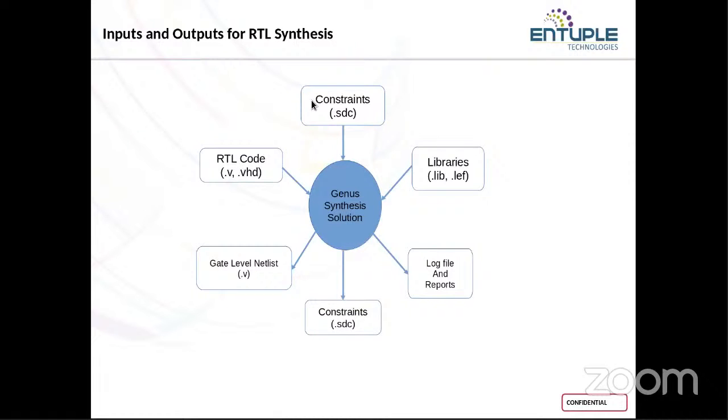So whatever SDC we are giving, that is user understandable, and whatever SDC the tool generates, that is your block level SDC file, which basically represents your individual block. So how can we explain what an individual block is? Whenever you are building a mobile chip, what are the things required? To perform any mobile functionality, what are the major things we look at?